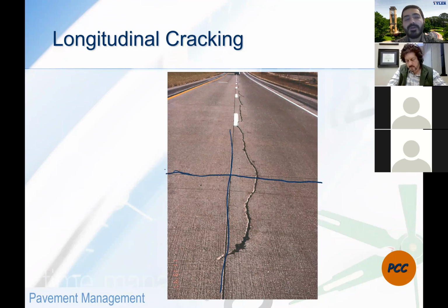Joint cuts are really what I like to call man-made cracks. Concrete as well as asphalt, but concrete is actually sometimes more dramatic, will expand and contract by changing temperature, mainly. So what happens is if you pour concrete and the contractor missed that period, sure enough, the concrete by itself, it doesn't need help from us human beings.